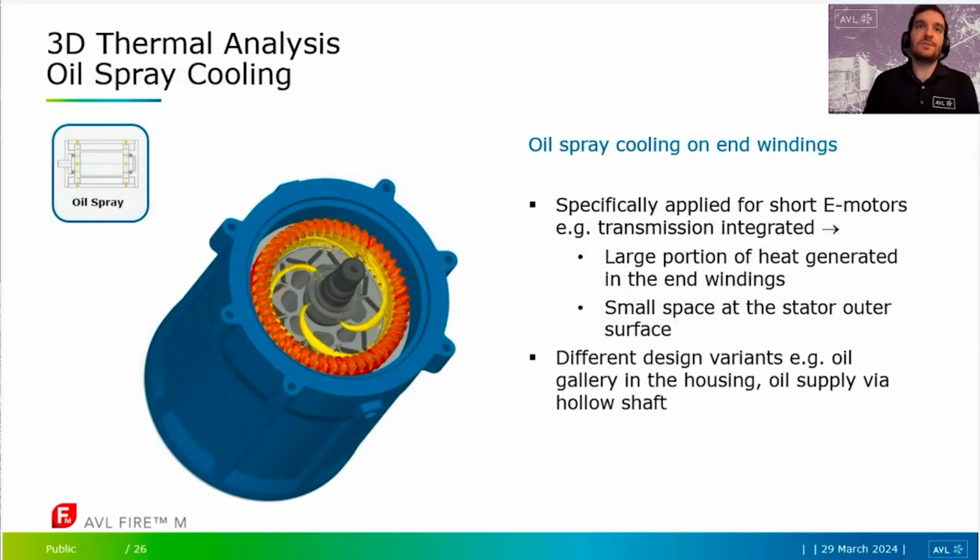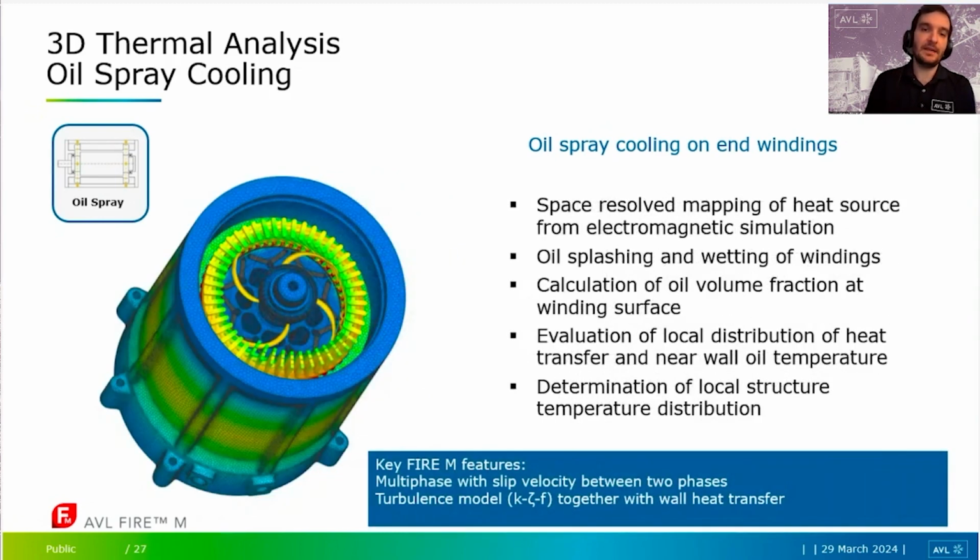The other thing we can do is oil spray analysis. So this is another thing that we see in the industry that is happening, is there's a large interest in understanding this, and this is a very complicated CFD because you have spray impinging on the windings, and this is something that could be a very sensitive factor for thermal management within your motor, because it's seen as more of a feature in a way. So this is something we do continuously here in AVL and FireM, and this is where I mentioned the sprays on the windings.